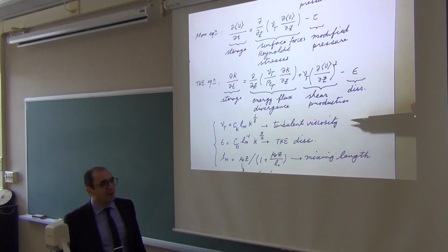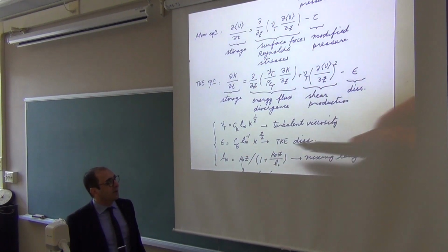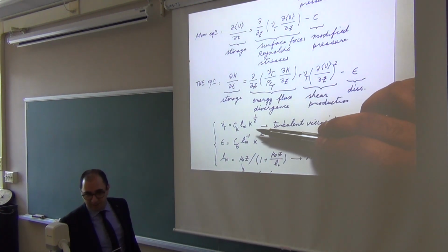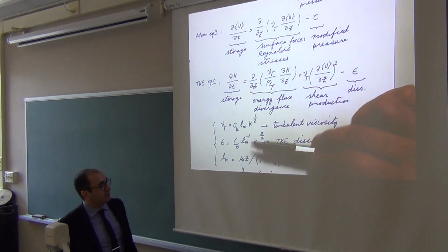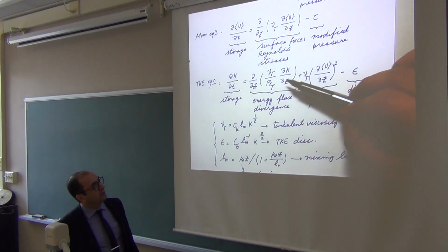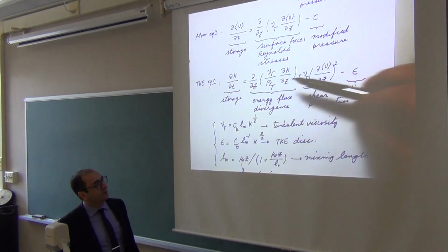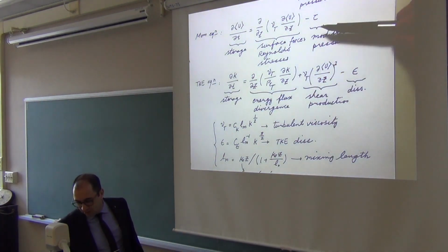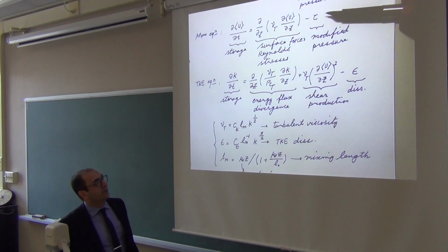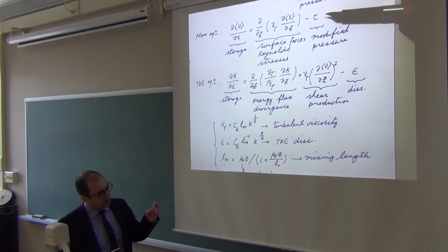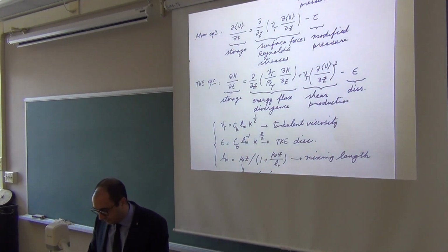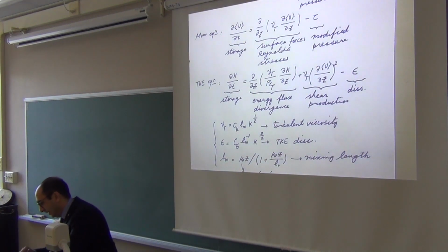Remember, it's not hard to handle this numerically. I mean, anytime I want nu t, I just calculate it, right? There's no computational cost in finding these other terms. The main computational cost is here, to have a numerical recipe to solve this equation. Of course, there's a cost with momentum too, but there's always that cost. Whatever you do, you always have to solve that equation. So we don't count it as the equation to categorize turbulence model. So this is a one equation turbulence model, also known as the KL. Let's derive it.